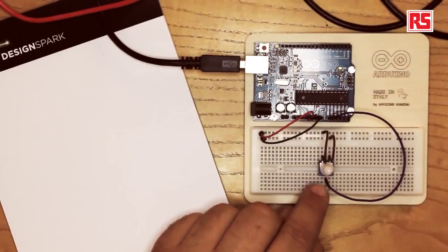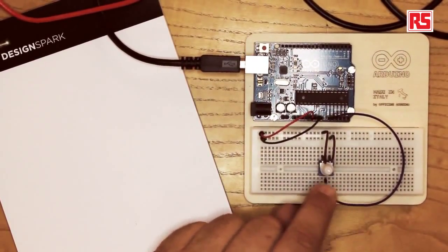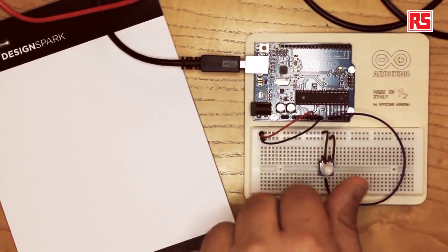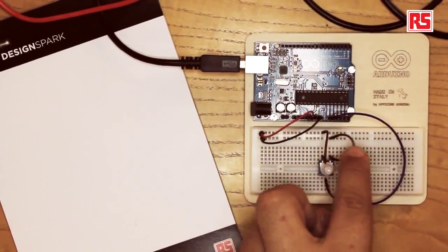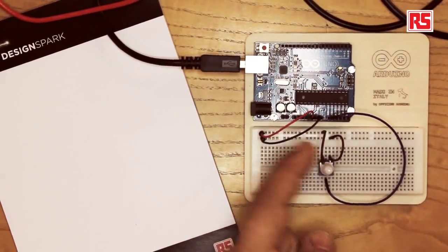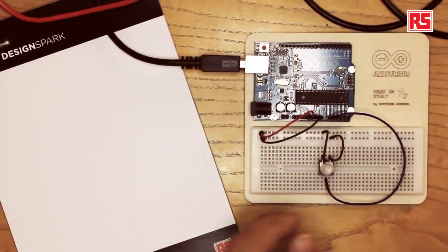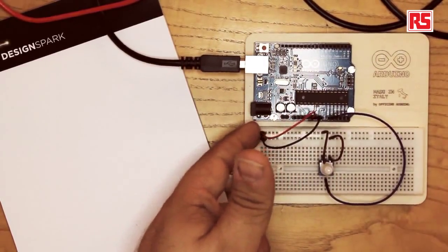Let's build the circuit first. So here, you can see that we have a potentiometer plugged into the breadboard, and we have one wire going from the potentiometer to the analog input 0 in order to read the value coming from the potentiometer. Then we have two wires connected to the potentiometer going to the plus and minus rail on the breadboard. And then we have a red and black wire going from those two rails to the 5-volt and ground signals